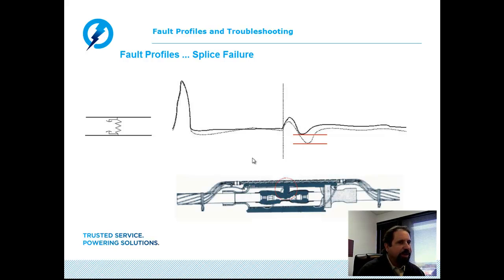If we're getting very weak kicks on our ammeter and voltmeter on our thumper during the discharge, that's the first clue that we're probably dealing with a large gap. So immediately in our minds we need to process: am I possibly dealing with a blowout or an open conductor type of fault, or am I maybe dealing with a fault that's within a termination or within a splice?